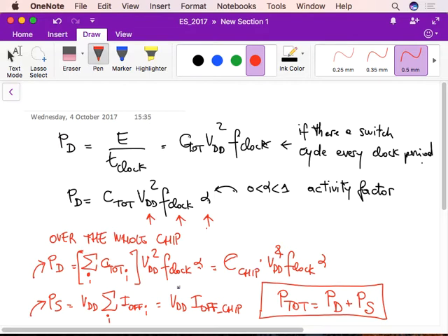You remember what we discussed before. So we need to reduce VDD because power consumption is important. Of course, we lose in performance, and then we have to gain in performance by improving something else. And so historically, the way in which we have compensated this reduction in performance due to the reduction of VDD has been by reducing L. Mainly by reducing L, we have increased the performance more than the reduction in performance that was given by the reduction of VDD.